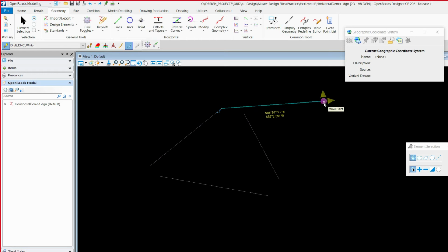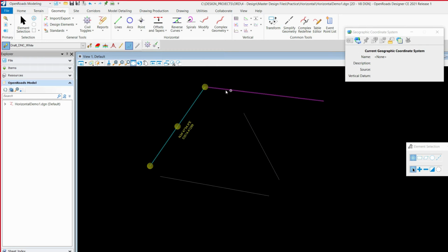And so if you move something like that, and say for example now you move one of these, well, now it's snapped and it stays, right? But other than that, since it's a line between points, it's saying, well, I'm trying to attach the first point of this line to the second point of this first line, and then the other point, I'm just making sure that I'm keeping the X and Y value that was input when this second line was drawn, right?